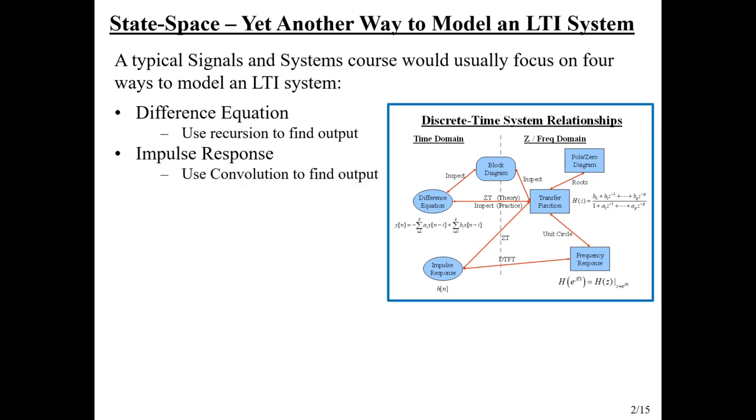Impulse response, that is something down here. That's h of n, also to the left of that line, so it's a time domain thing. We generally don't use this to compute the output in an actual system, but we might lay it out to think about it. Although, having said that, we will when we try to emulate the reverb of a room.